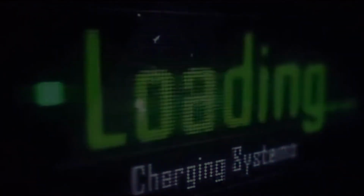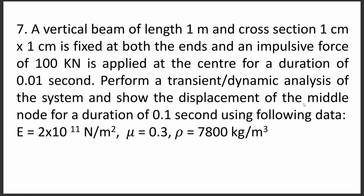Let's get started. Hello, today I'm going to show dynamic analysis or transient analysis of a beam using ANSYS Mechanical APDL. Let us see the statement of the problem. The problem states that a vertical beam of length 1 meter and cross section 1 centimeter by 1 centimeter is fixed at both the ends, and an impulsive force of 100 kN is applied at the center for a duration of 0.01 second. Perform a transient or dynamic analysis of the system and show the displacement of the middle node for a duration of 0.1 second using the following data.